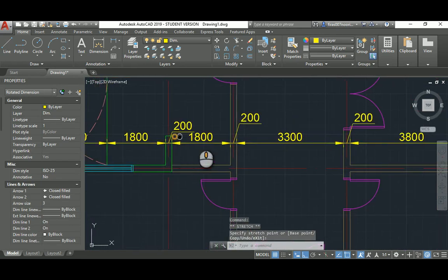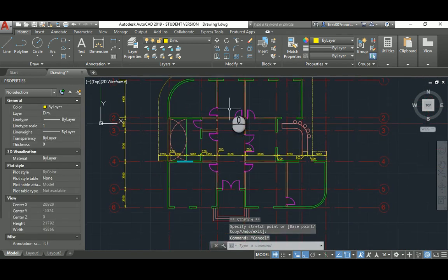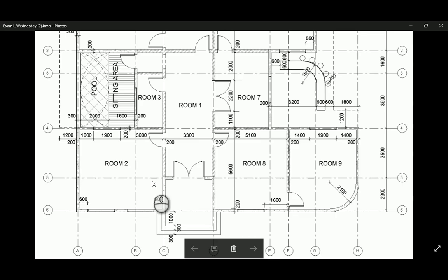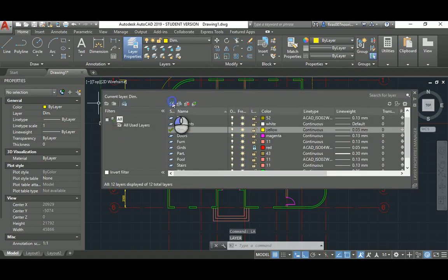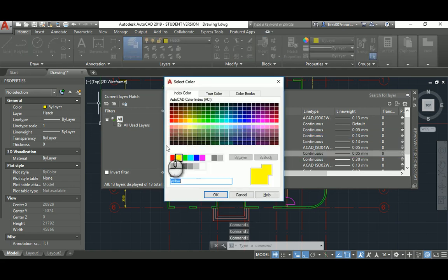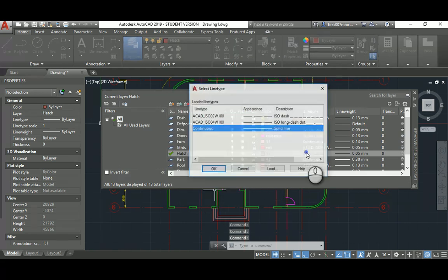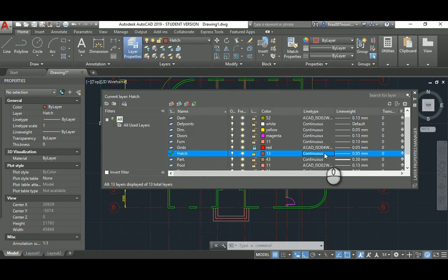As you can see, that's the dimension. And you can go ahead and do the vertical lines just the same way. What else? The hatch. So let's go ahead and create a layer. I'll call it hatch. Make it current. Change the color. And reduce the size.